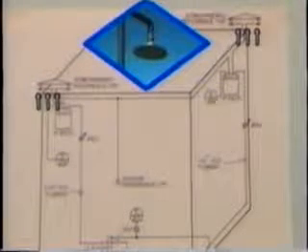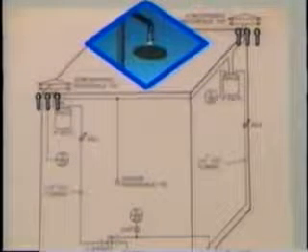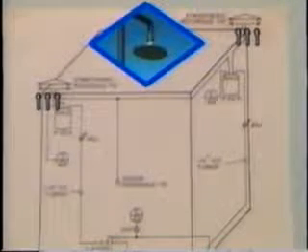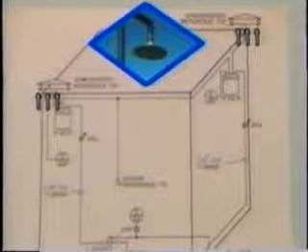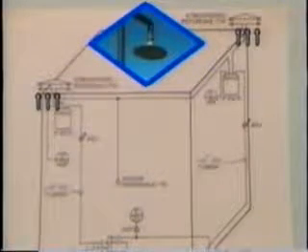This method, utilizing the higher of the two signals provided from the differential pressure transmitter connected to these sensors, will provide a relatively accurate atmospheric reference while substantially reducing the height above the building the sensing tips are to be located. Now, let's look at multiple point self-averaging pitot tube stations.